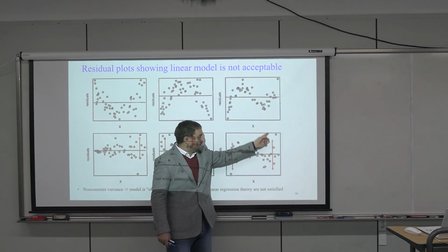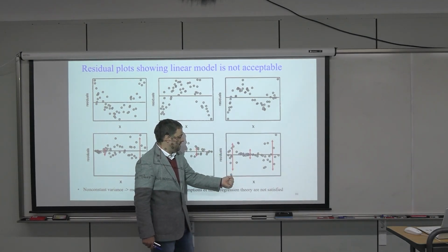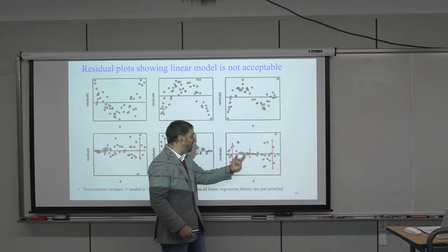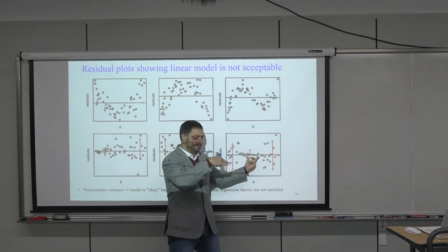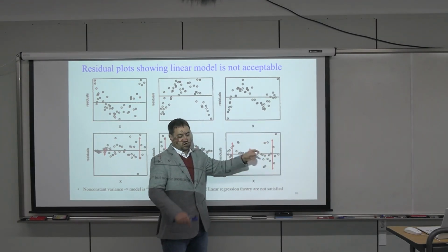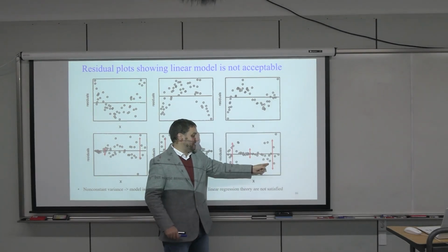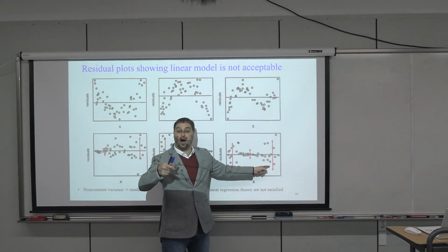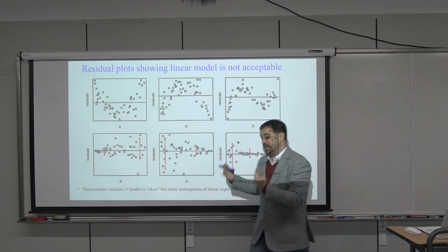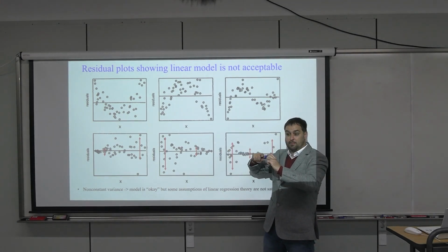And cavitation is very oscillatory. So here you might be at low mass flow rates, in the transition region from laminar to turbulent flow, now you're in nice turbulent flow, and now you're getting cavitation. Your measurement device might be really accurate and precise, but the actual physical phenomenon, the underlying function, is oscillatory. The example I just gave is fluid flow in a pipe. At low velocities, you're laminar.